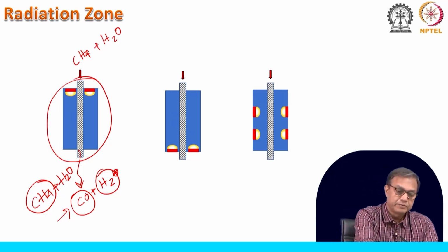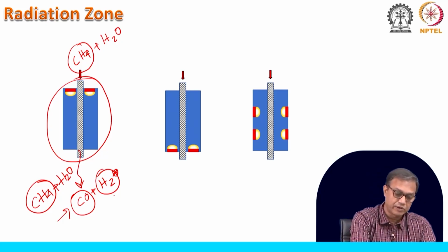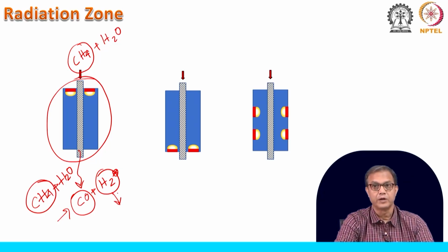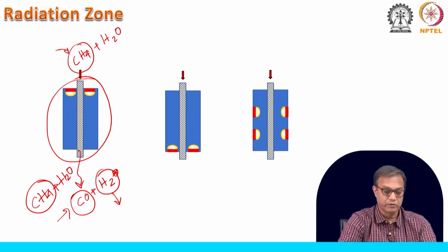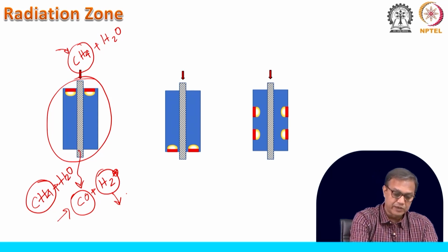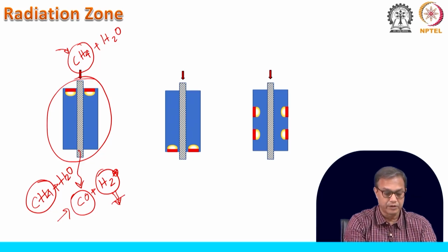But this methane generally we try to put under pressure, because that will give us this H2 under pressurized condition, though the thermodynamics will tell that methane at low pressure would have been better. But finally, as we understand, this hydrogen has to be stored in a compressed condition, or it has to be liquefied.